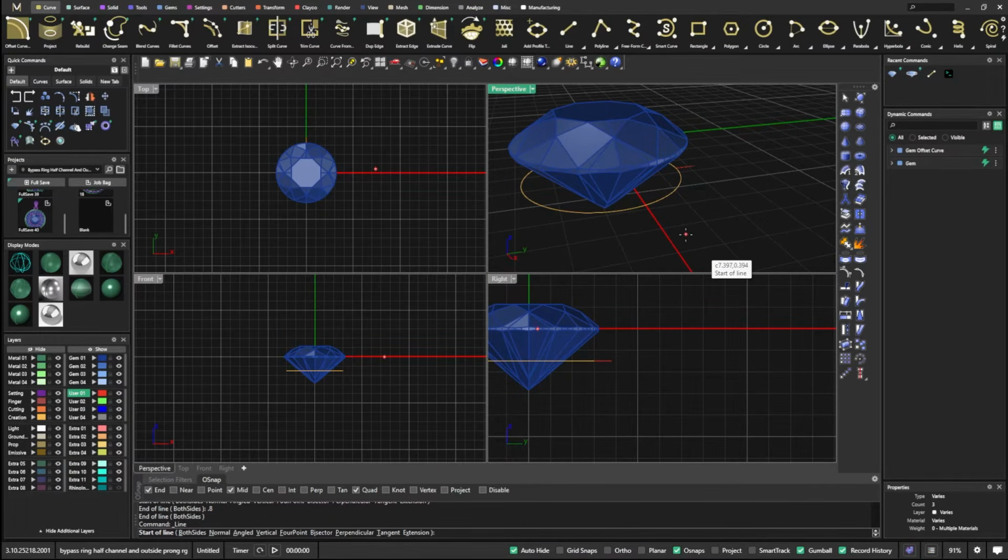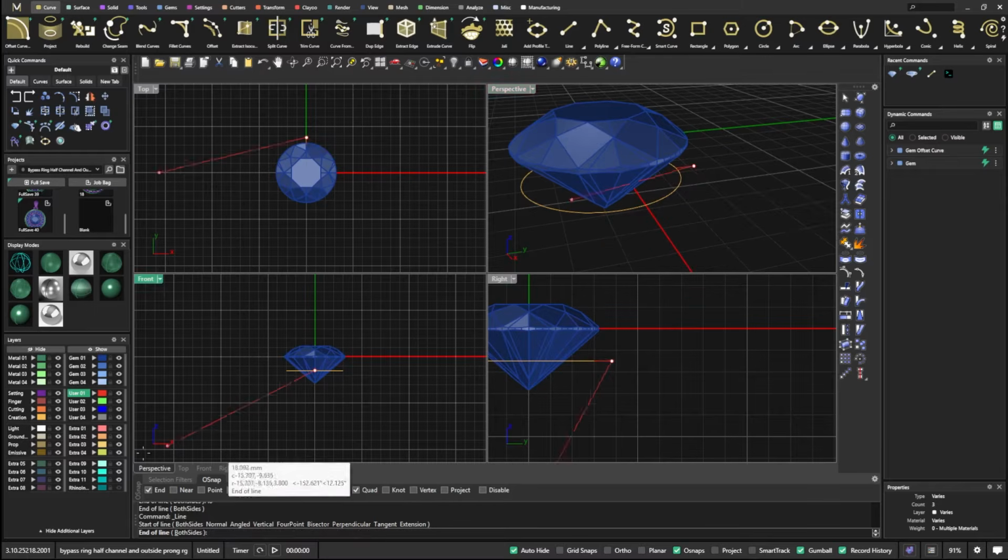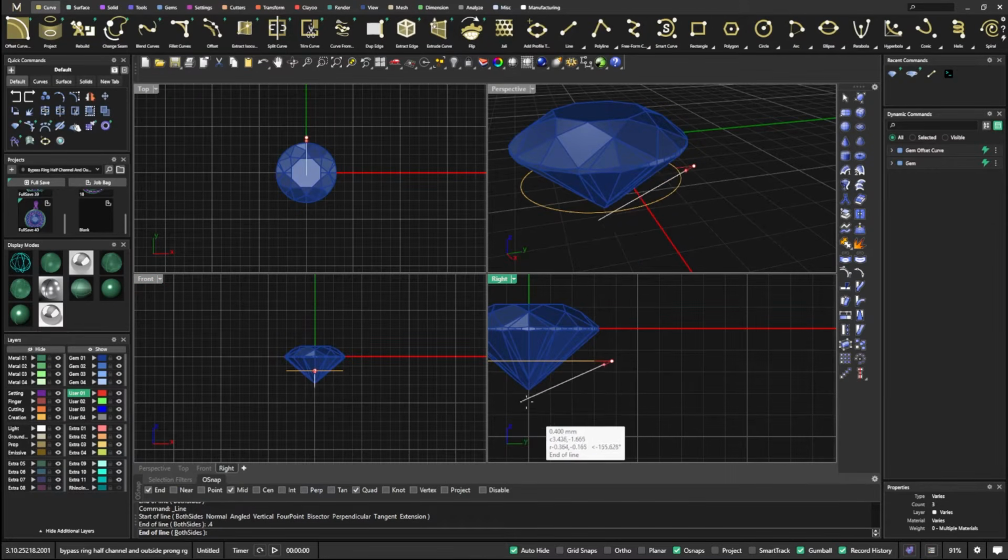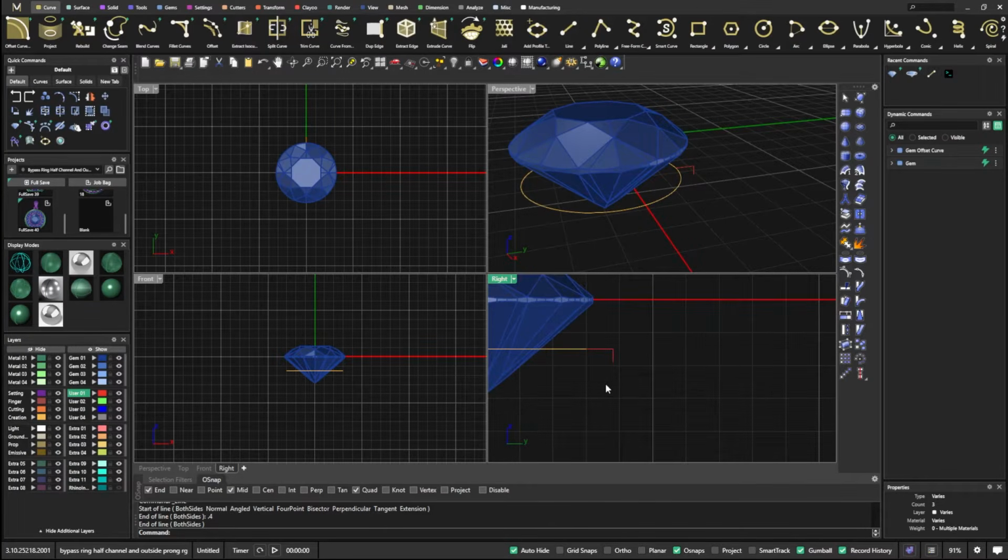I'm going to right click, bring back that line curve, and snap right there to the end of it with my end snaps on, and I'm going to say I want to drop it down 0.4 and hit enter. Then I can hold down shift and it'll lock it into the 45 and 90 degree angle area, and we'll take that.